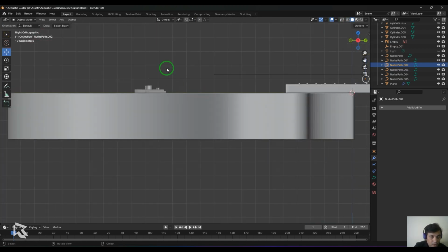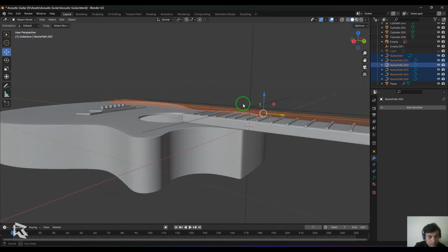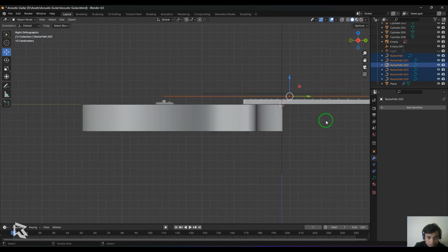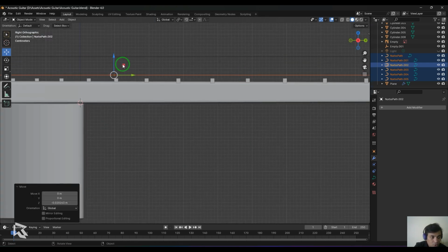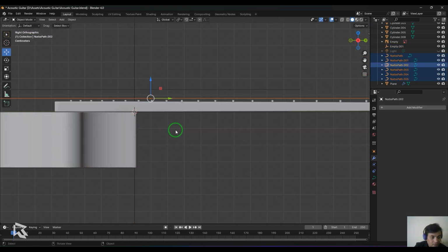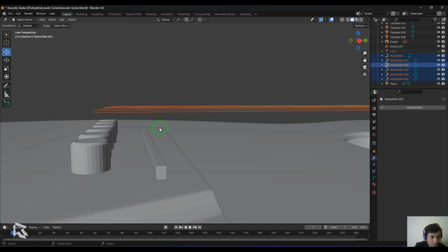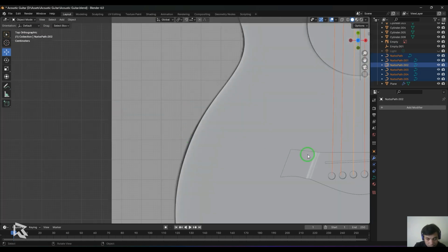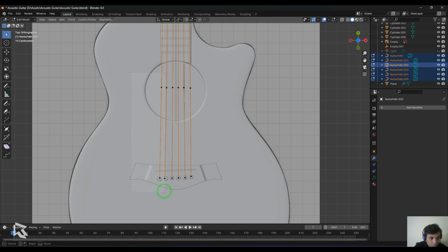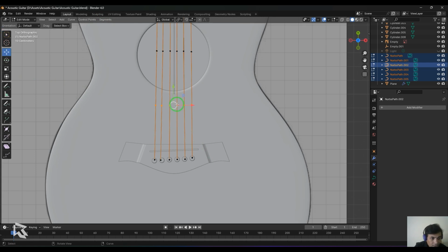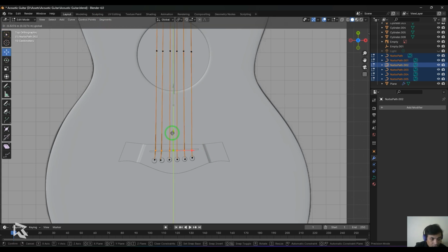I could see all these strings here, which are slightly above. So I'm just moving it, which is almost close to these particular handles. Now what I'm going to do is select these two points here, and we have a tool called subdivide, so I subdivide up to this level.